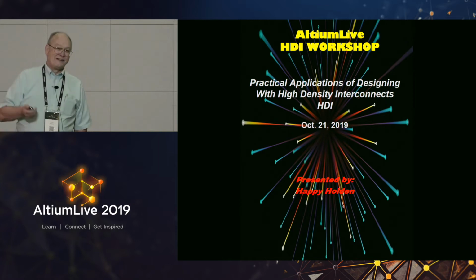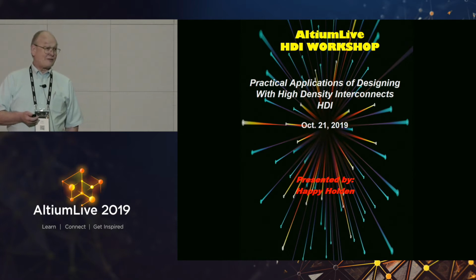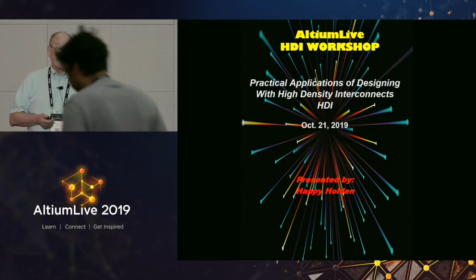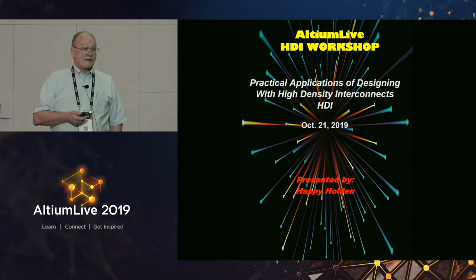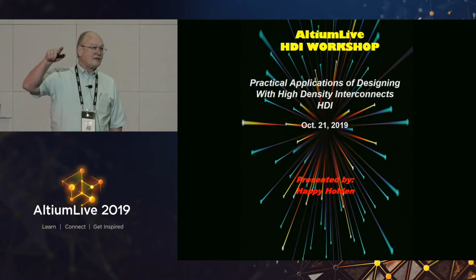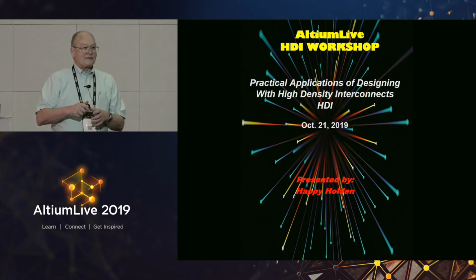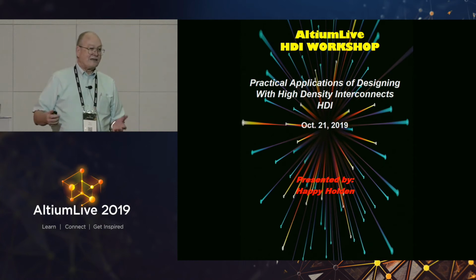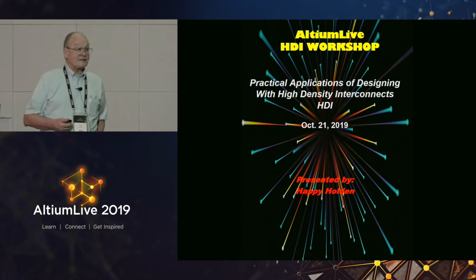So you get the pleasure in a few years of working with up to 5,000 pins as a device, because you would think that with 2 billion transistors, you could complete everything on the chip. But you keep adding more functionality and wider bus sizes, and the number of signal pins keeps going up, and they have to have more and more ground pins for the signal integrity.